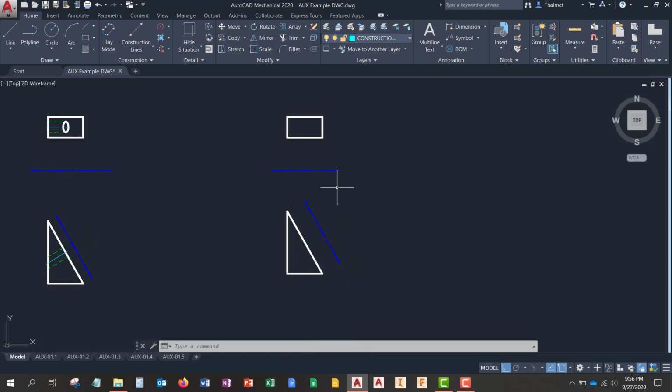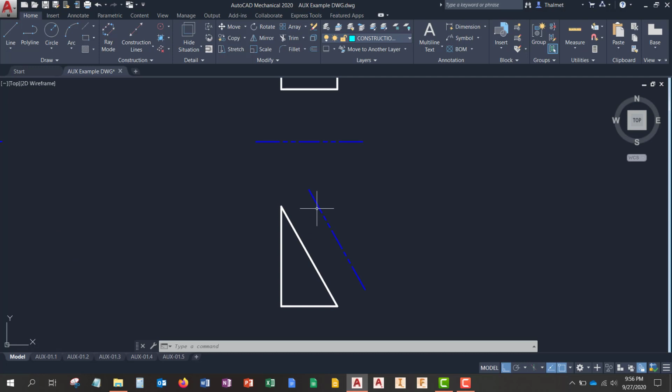So essentially what I'm going to do, like I said, is take the points of that, translate it to my front view, and then again translate that to an auxiliary view. So what I've done here is I've created another phantom line that I'm using as a fold line that is parallel to this surface. Again, where I see it as an edge.